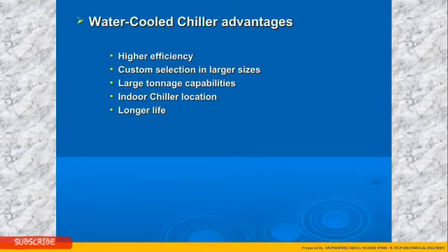Now let us see the advantage of water-cooled chillers. Higher efficiency, custom selection in large sizes, large internal capacities, indoor chiller location, and longer life. For sure, definitely the initial installation cost for a water-cooled system is higher than another HVAC system. But in the long run, and when you consider the lifetime cost analysis, this is the most efficient system as of now.